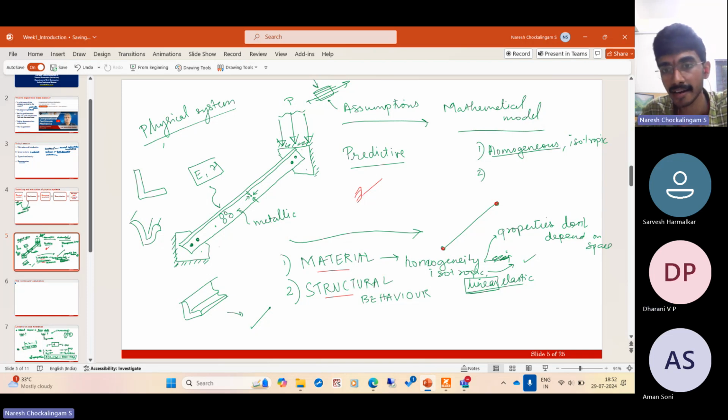Okay, I can tell that that's a little ambiguous. If these are bolted holes, these will allow rotation. So bolted connections typically allow rotations. For a moment resisting connection, you need to weld this, right? You need to stop it from rotating. So since I just have one line of bolts in the mid axis, it will allow certain rotation. So a good idealization would be this.